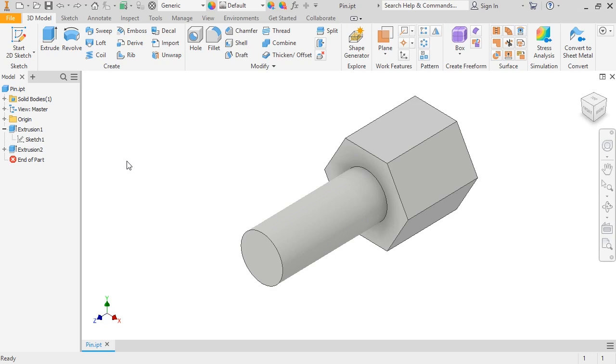The first change that I need to make then is to change the diameter of the sketch. Since I just need to change an existing dimension in the sketch and not add or remove any geometry, I can use a different method to make this edit. I'll select the cylinder in the graphics area, and in the shortcut menu that appears, you can see that I have options to edit the extrude, edit the sketch, share the sketch, or make the sketch visible. This menu is a great way to intuitively make edits, since you just need to select the geometry you want to change. But the option I want to use for now is Make Sketch Visible.